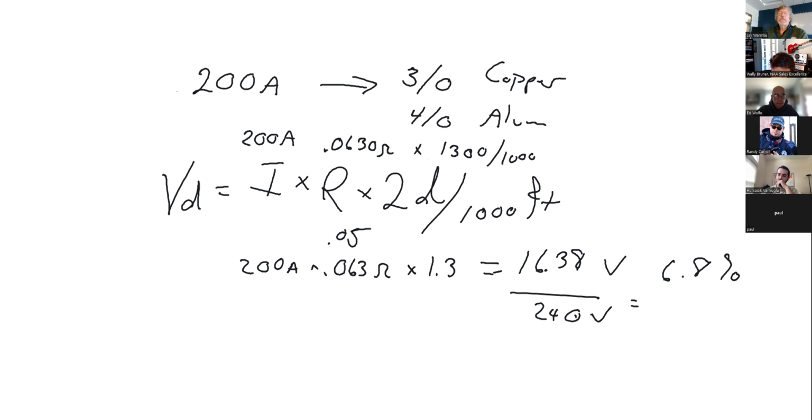So the first step here is of course sizing it based on the amperage that you're going to be sending through. And is 200 amps, I mean, how big a house are you talking about? 2,500 square feet. Okay, so it's not a cabin in the woods kind of thing. No, it's a real home. Okay, so 200 amp service is probably legit. You're going to be burying the wire, right? Correct. So you're not going to have temperature issues there.